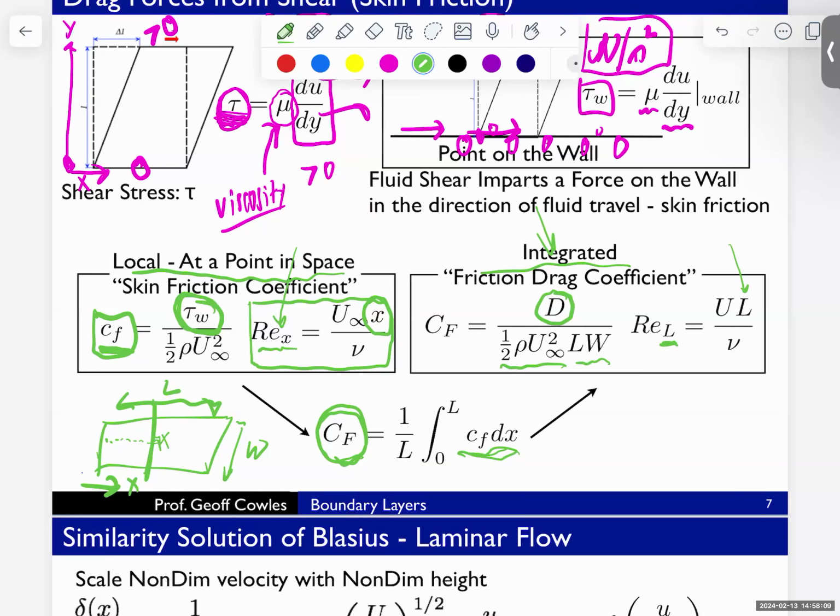In this case, L. Using this Reynolds number, we're going to plop that in a formula, and we'll see those in a second. And that will give us a skin friction coefficient here, from which I can do lots of stuff. For example, if I want to know the actual drag, given the skin friction coefficient, given the stuff in the denominator, I can compute, and I'm going to circle in blue here, this D. This will be the drag due to skin friction. And that's probably the primary thing we want to get out of this.